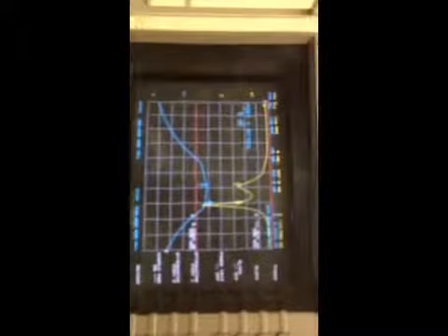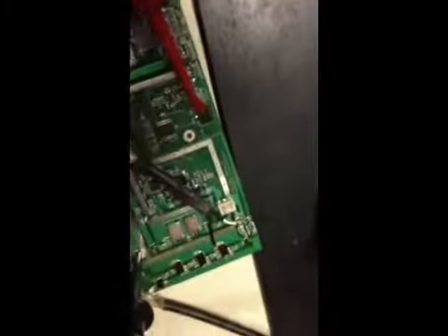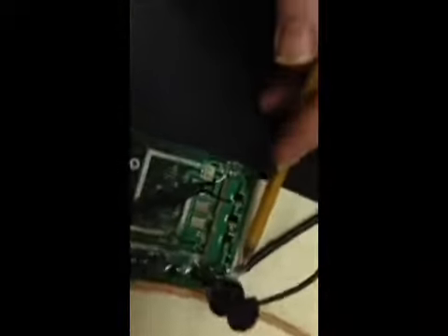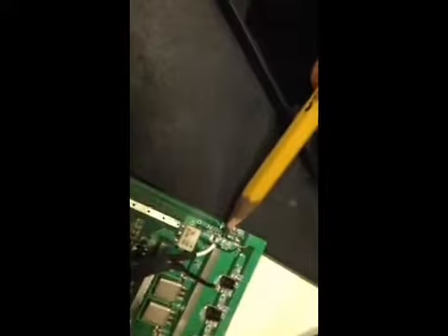Alrighty, now we've hooked up and we're looking at the glide slope frequencies from 329 megahertz to 335 megahertz. You can see that we are hooked from the input port here, following this circuit path, through this amplifier here, to this easy to break point in the circuit.